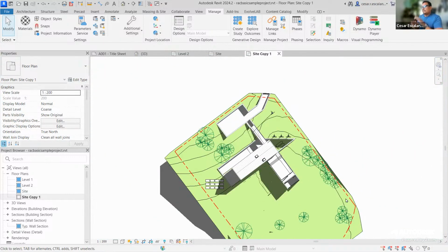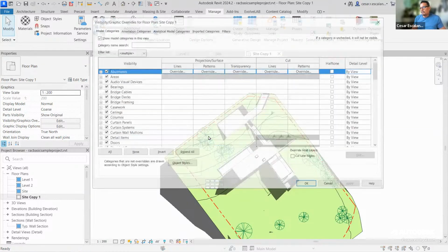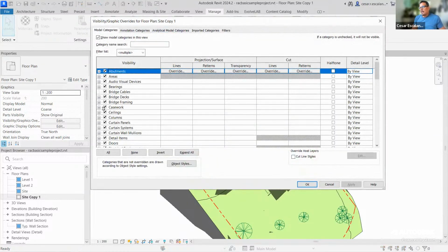Okay, so I'm tweaking the line weights, the color, the line settings to serve a specific purpose in Revit. And visibility graphics is exactly what helps us achieve that. So I want you to understand this before we move forward, because VG is going to be something we use almost in every class.